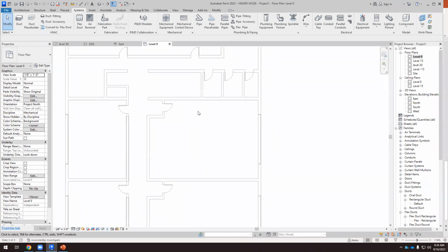So if we have a diffuser here, a supply diffuser, and then I have a return diffuser there, this can happen if I supply air and I have this return diffuser very close. So it's possible that this happens, that the flow goes this way and then it finds a return diffuser very close and it doesn't reach the occupied area. So this is a big mistake.